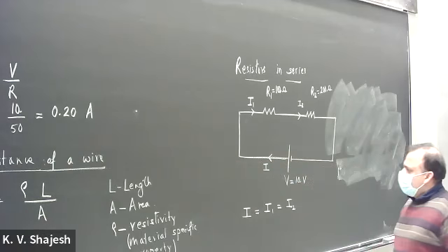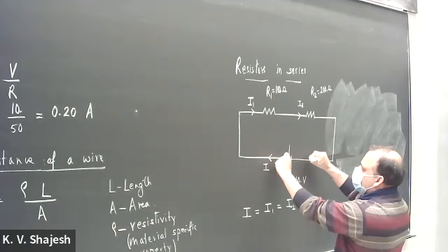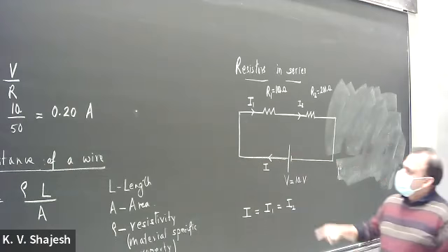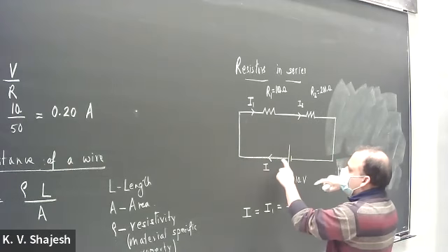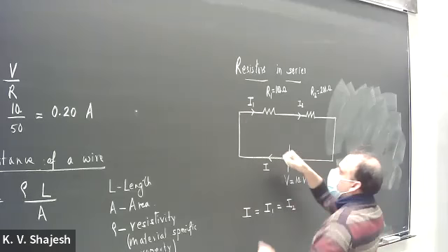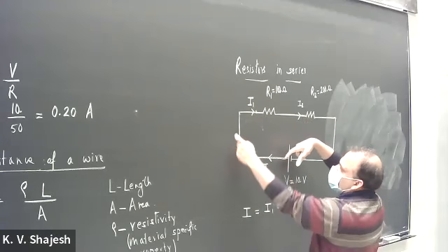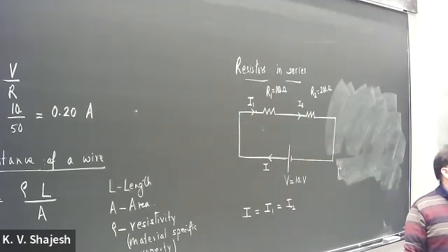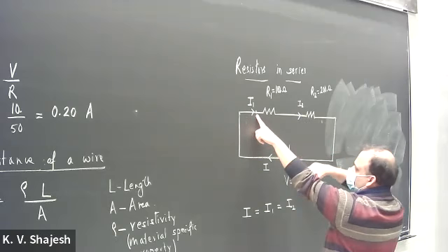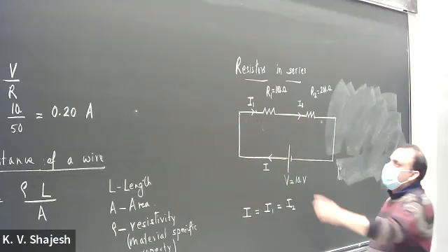But once we have that, we still have the property that whatever is the potential difference between these two polarities of the battery, that has to distribute along this. So this is at a high potential, low potential. This high potential shows up here, right? Those 2 points are at the same potential because this is just a metallic wire. Metallic wire has the same potential across that. So that's a high potential. That's a low potential because that's connected to the battery. And that has to be distributed over that in a linear fashion.